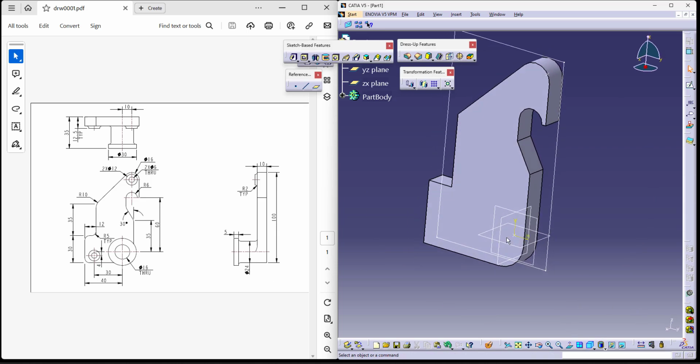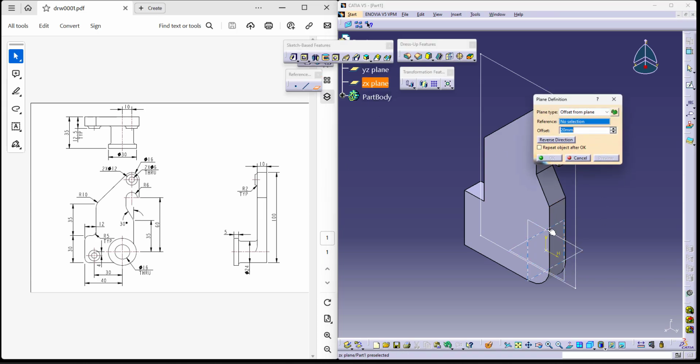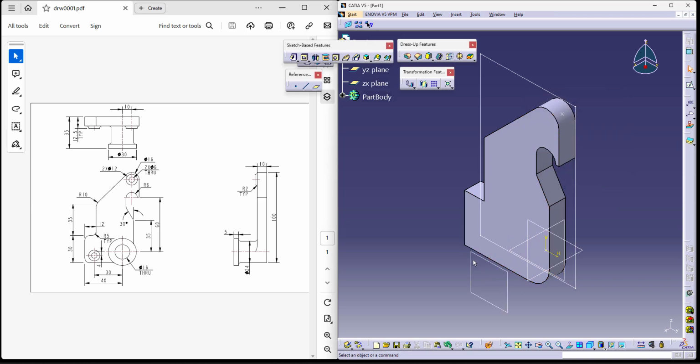Now, while building these circles, while adding these circles, we must realize that the dimension is given with respect to the base. So whenever the dimension is given in that scenario, please do not subtract the dimension and take 25, because whenever you attend a tool test, that will become a big mistake and you will be rejected instantly. Instead, what you can do is you can directly take a plane at 35 and then work on this plane.